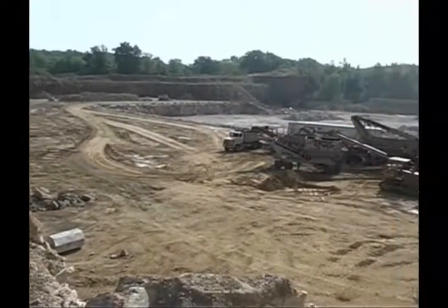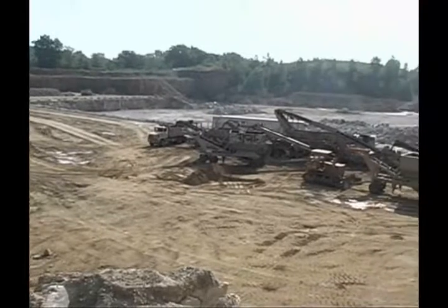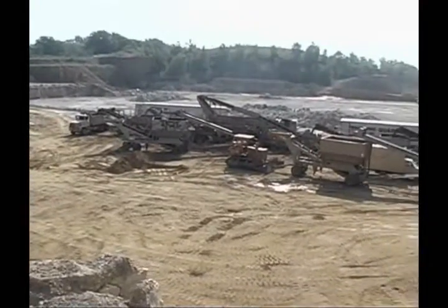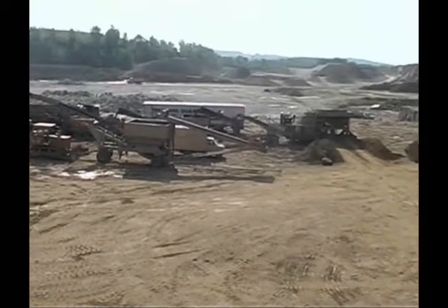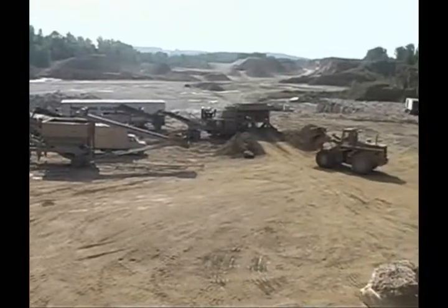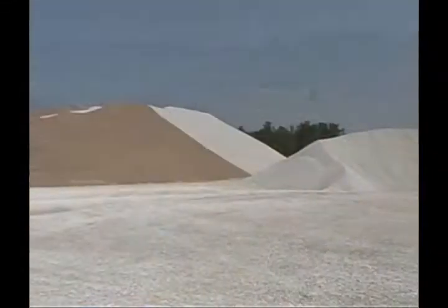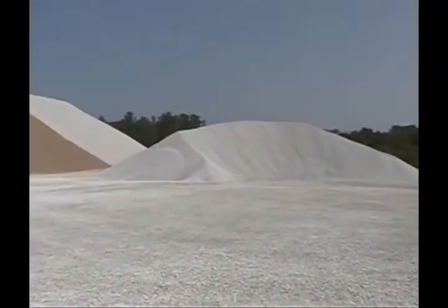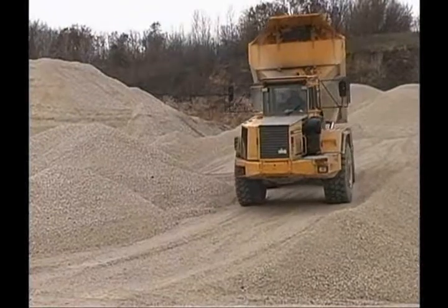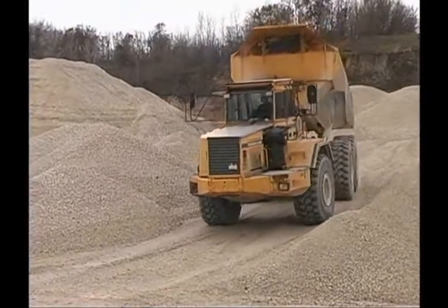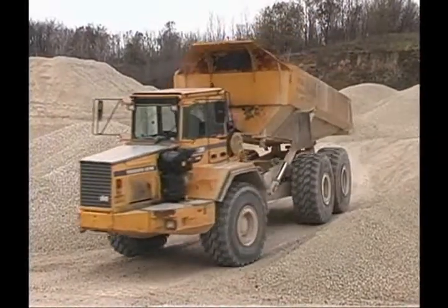An important part of an aggregate technician's duties is to visually inspect all aspects of the production process. This not only includes the quarry ledges and crushing operation, but also the stockpiling procedure. Care should be taken to ensure the stockpiles are created and maintained properly. Stockpiles should be identified to avoid confusion. Driving on stockpiles should be held to a minimum, as this could cause degradation of the material.